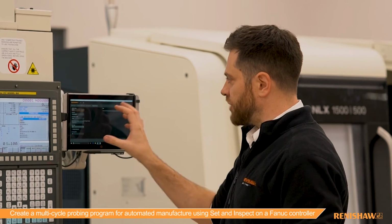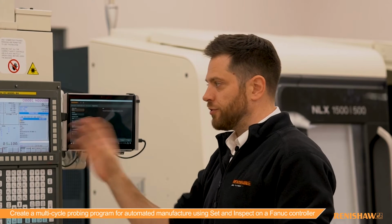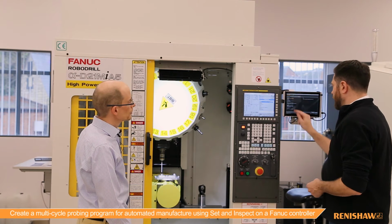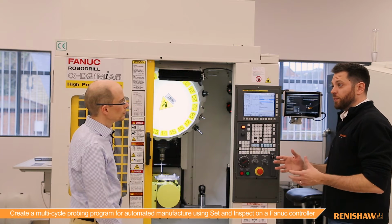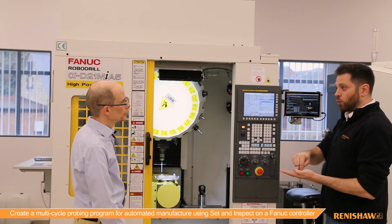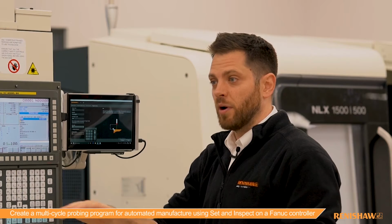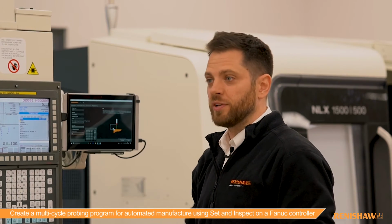Great. So initially we have to set up some information. We'd give it an NC program number, so that it can be called via your cutting program. Also identifying which work coordinate system will be active, that we're going to be probing in. And also something here where the customer can define their retract position. So in the whole ethos of wanting to make this simple, when you add a feature to the program, it'll automatically move to this retract height and then move to each of these features at that same height. That can be optimized for more advanced users, but straight out of the gate, it's the simplest way to work.